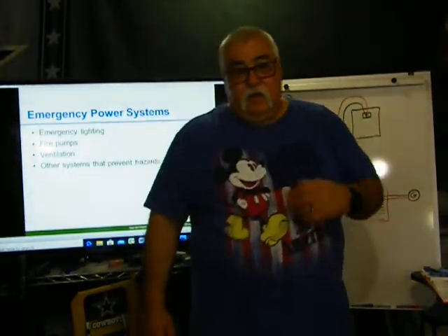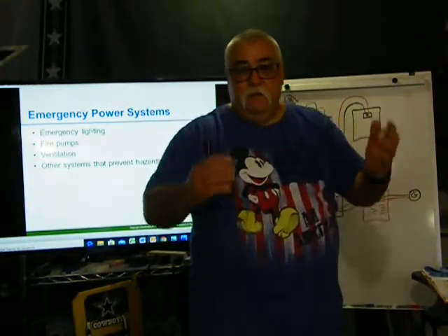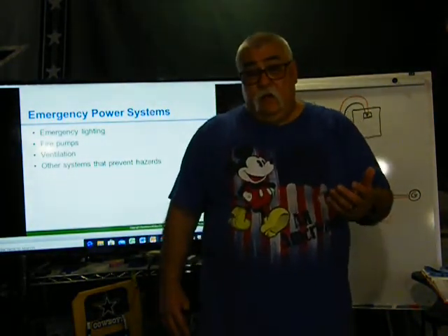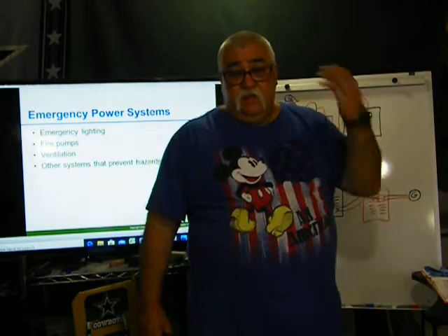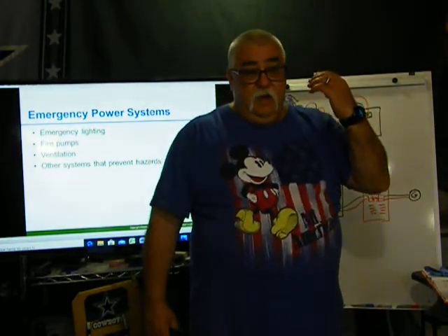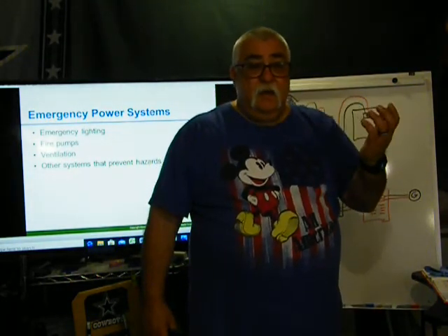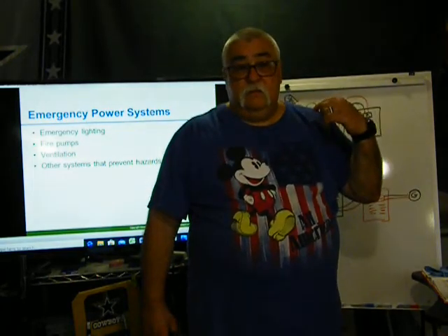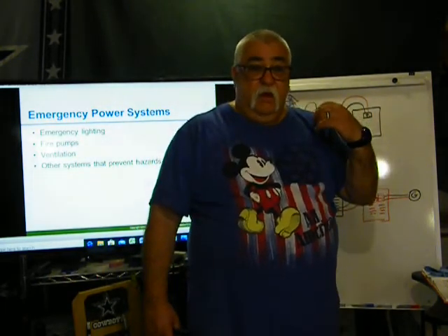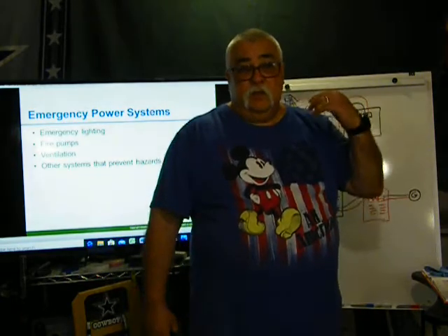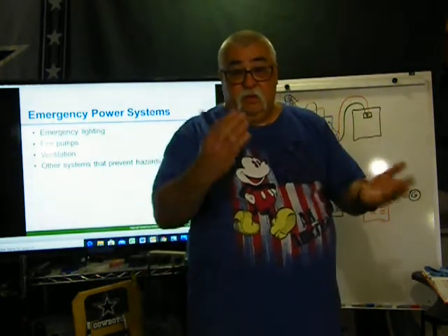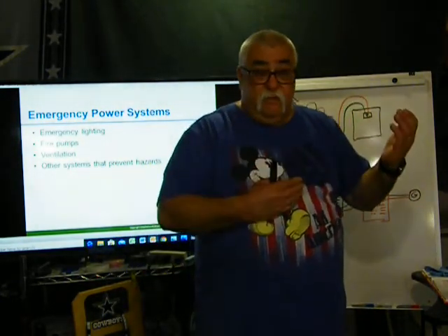So again, anything that helps people get out of the building. Ventilation, where do you want the ventilation? Well, sometimes as the fans come on, they may have a relay that turns the fans in reverse. So in case it goes into an alarm, the fans start running in reverse. We talked about motors, and we're talking about reversing relays.